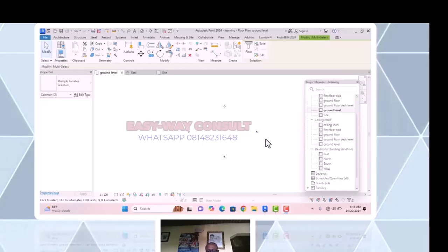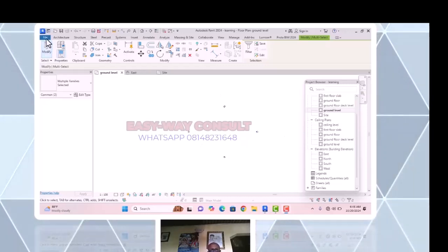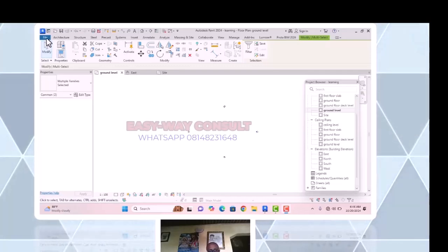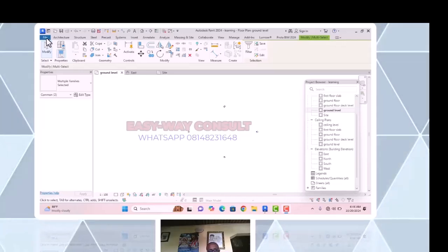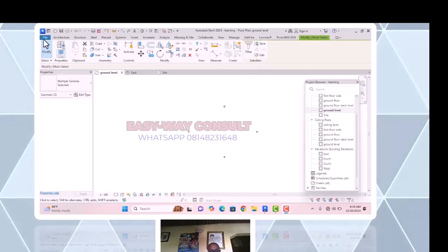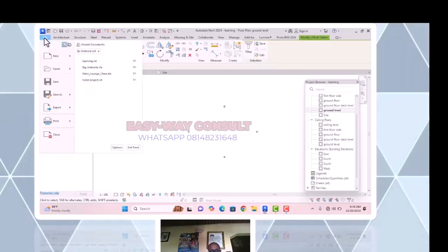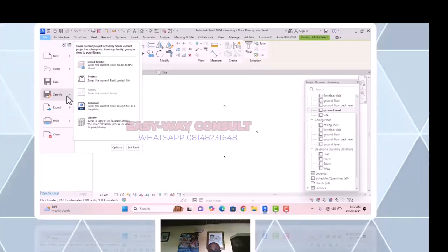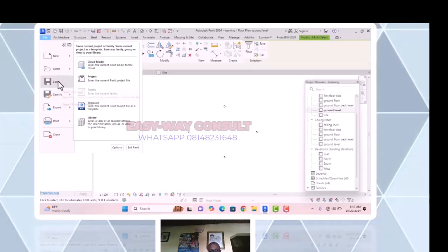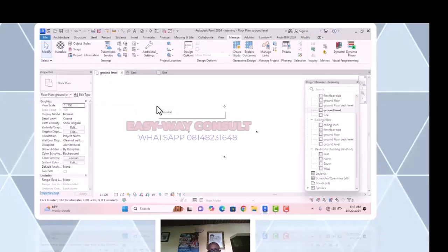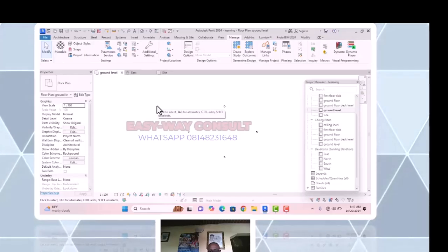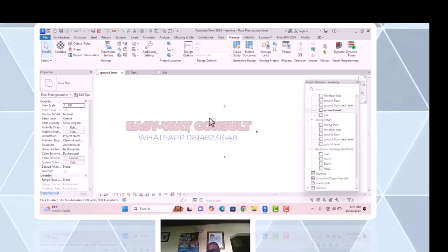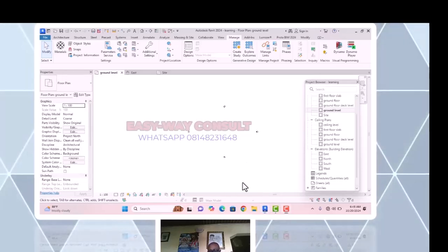So it is always advisable when you have created the level and everything, you save your work, but it has already automatically shown us how to save. I hope you saw how I save, but to save your work on Revit, you go to file. When you go to file, you say save as. It is when you have not saved it, but when you have saved and named it, you can always go to this save. So whatever happens to your computer, as you work a little, you go back to file, you save. It is always advisable to save whenever you are working.